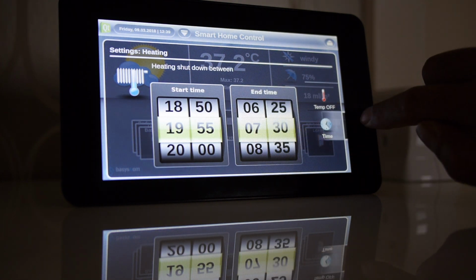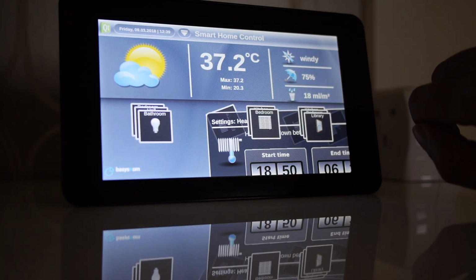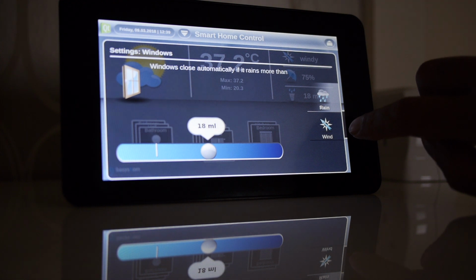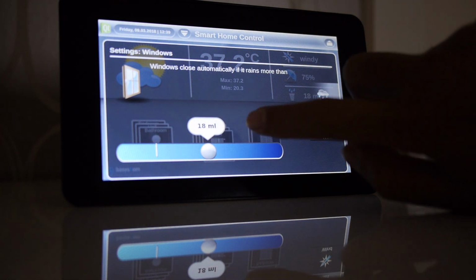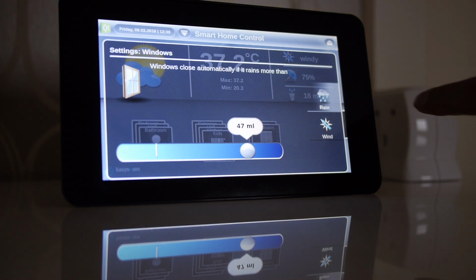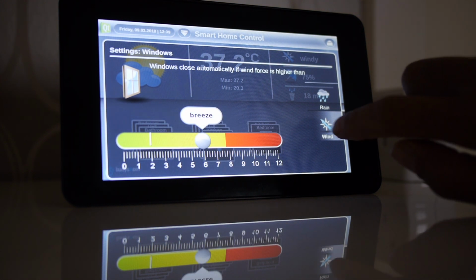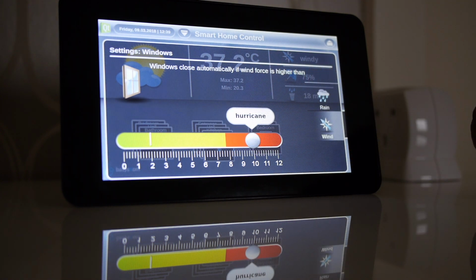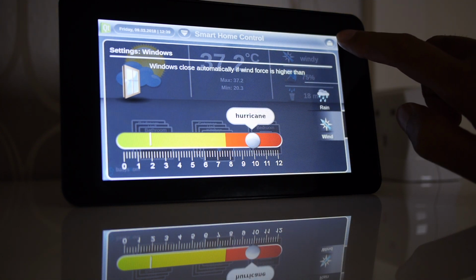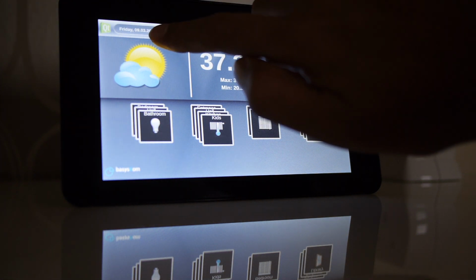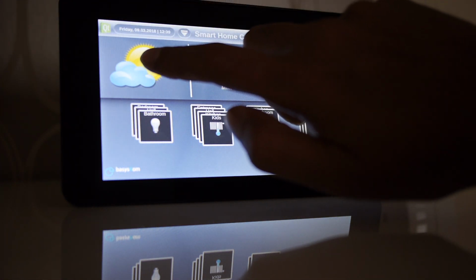One thing I'll add is, since there is no X11 manager in this Linux image, we start our applications with the platform argument that has to be passed to the application: platform linuxfb. So we are using the Linux frame buffer argument to start our application. The graphics look very nice really.